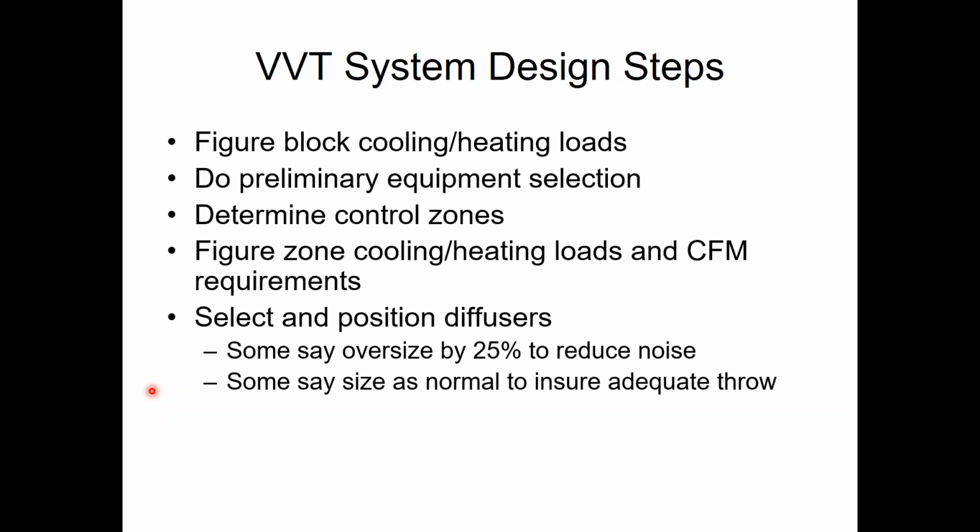In cases where you have those noise issues, it's usually because that damper is the only one calling for cooling and all the other dampers are shut. And that only typically happens when you've done a bad job of laying out your zones.